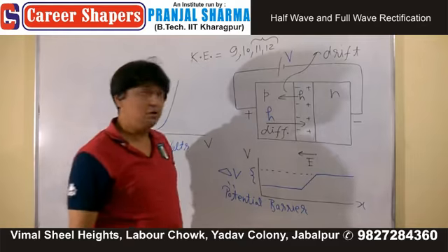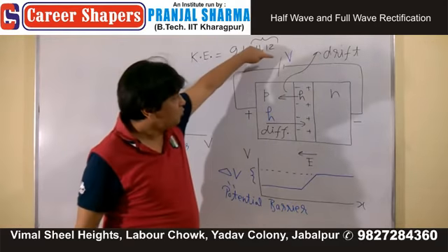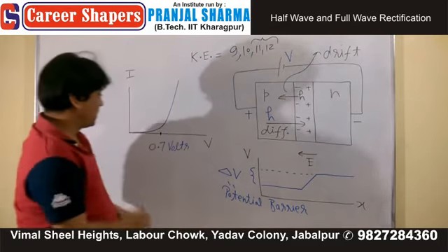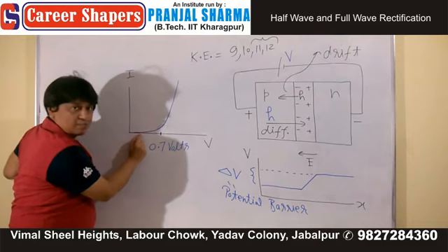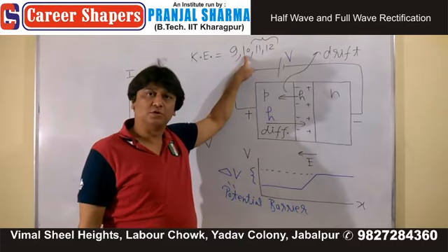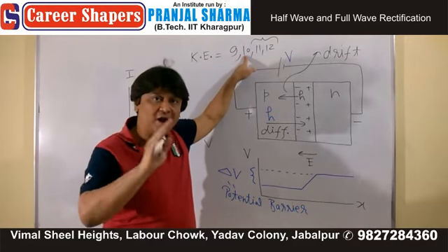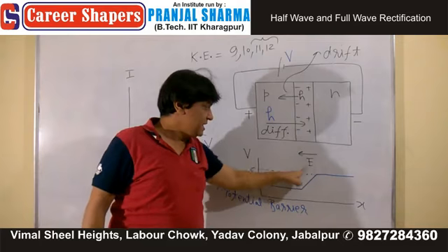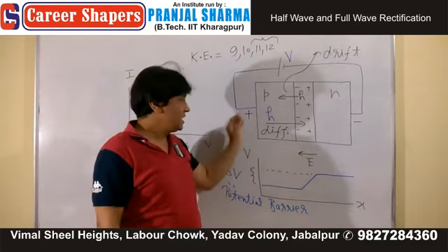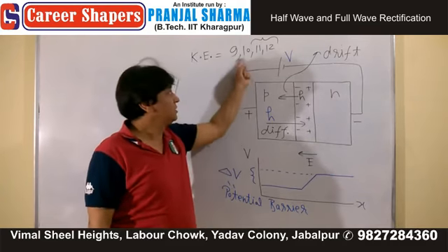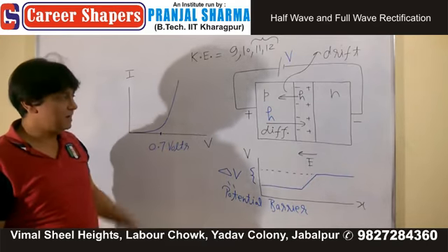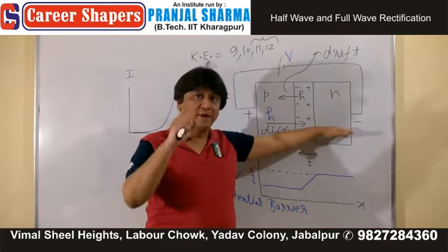If you keep your temperature constant, at a constant rate this whole electron-hole pair generation will continue. You can control diffusion current with the help of biasing voltage. The moment you increase your biasing voltage, you're basically increasing the kinetic energy of these holes. You don't have to overcome this entire electric field. A little bit of extra energy, these will move and will increase your diffusion current. There will be a net current in this direction.